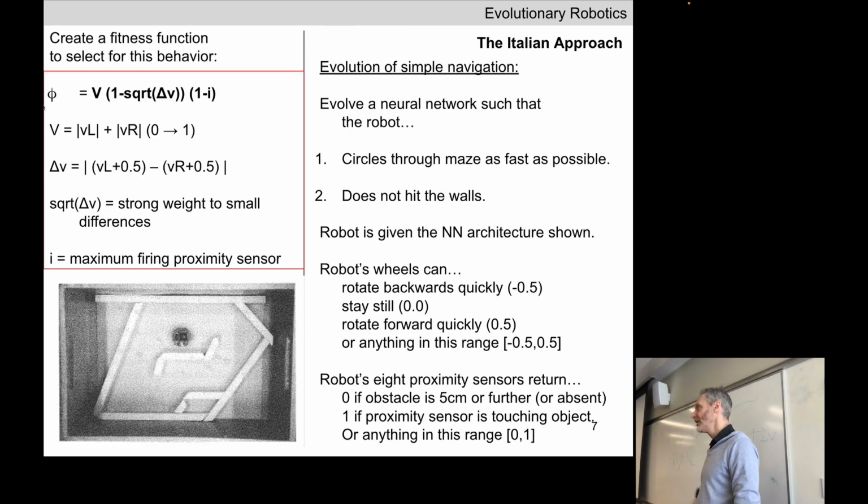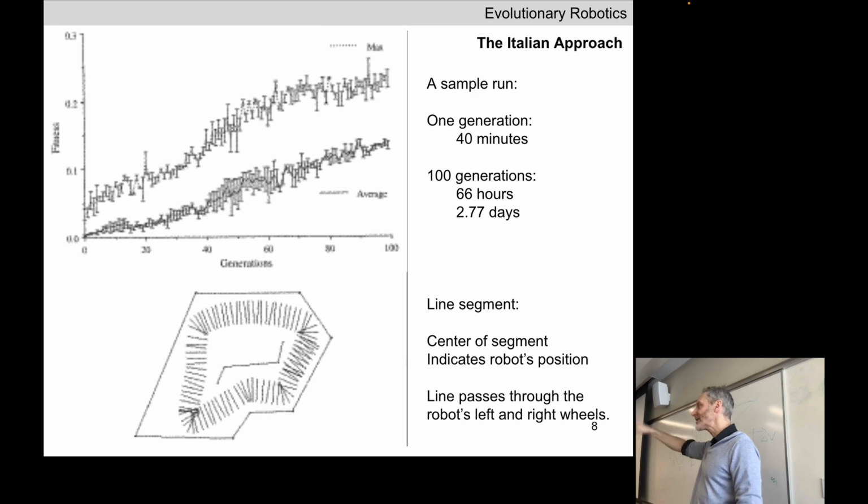They deleted half of those vectors, the ones that got lower than average phi. And then they made randomly modified copies of the surviving vectors. For all of those new vectors, they downloaded each one onto the robot for 10 seconds apiece and continued this process for 100 generations, which took 66 hours, or a little under 3 days in total. You can see why you're using a physics engine and not doing this all by hand on a physical robot.